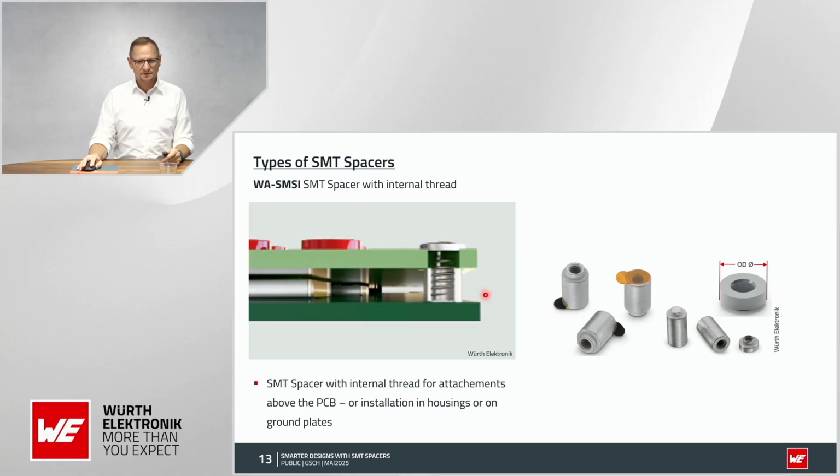However, this picture is not absolutely accurate, as there is a kind of shank that you can see here, and this goes into the bore hole of the PCB for 1.4 millimeters in the standard types. The PCBs usually have a thickness of 1.55 to 1.6 millimeters. So this will end before the PCB ends, so the bottom side of the PCB is absolutely flat.